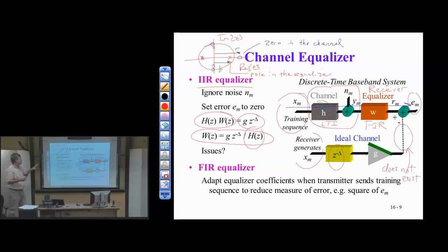Okay. So given an FIR channel model for the LTI component, I can give you the IIR equalizer. And it's all pass except wherever the zeros of the channel are on the unit circle. I can't help you right around that frequency value.